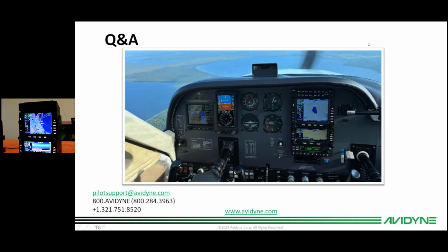If maybe we can't hear Tom, we have one that says there's a recommendation to always start the Stratus 3 first before turning on the avionics switch in ForeFlight. Works like a champ. Yes, that's a very good pre-flight action, and the reason for that is the IFD will remember the last settings that you changed. So if the last thing you did was connect to a Stratus, it'll remember that at startup. The first thing it's going to look for is that Stratus signal.